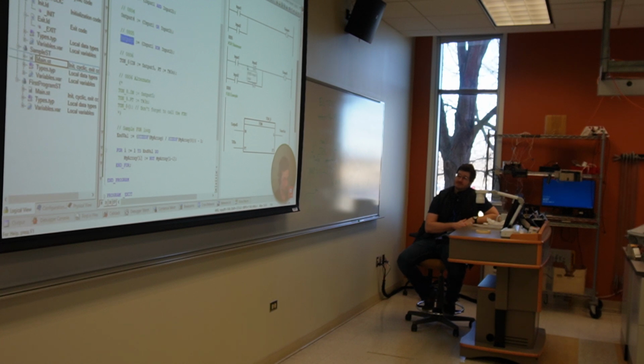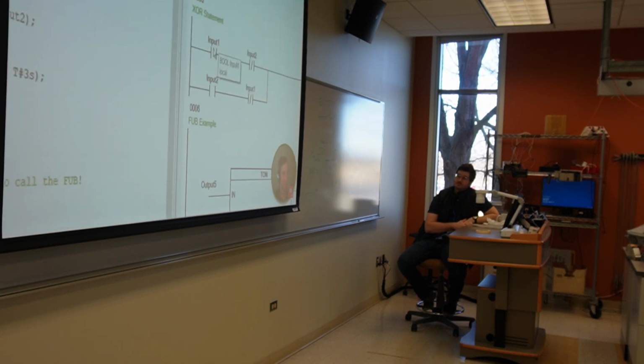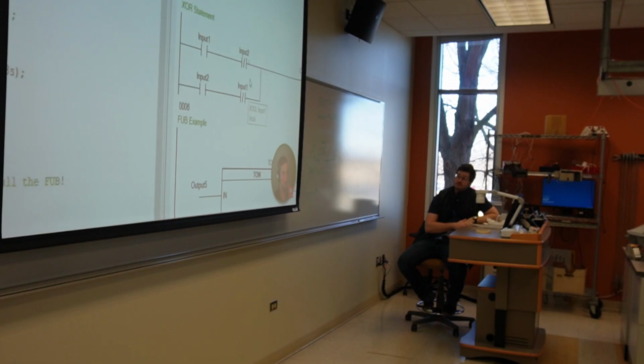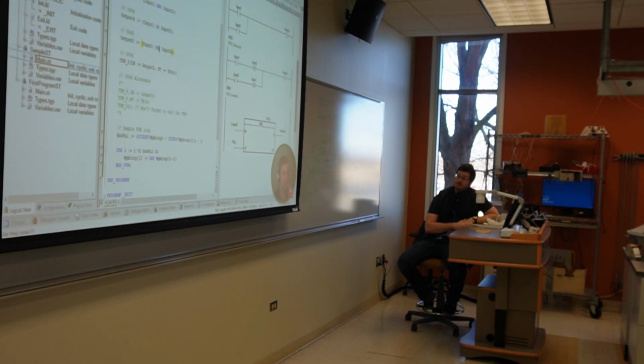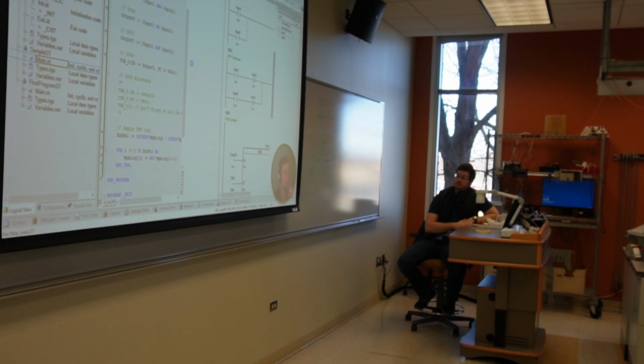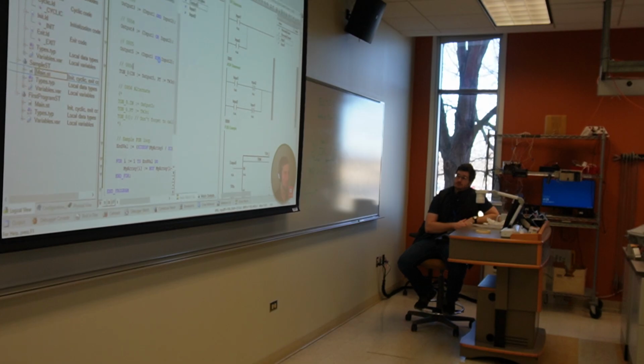We don't have to do this kind of funky, normally open, normally closed stuff. We can actually just type XOR. So that one's a little bit easier. So input 1 XOR input 2. And we can take a quick look at that just to prove that it works, since it's a little bit of a trickier one. As our watch window opens up here, I'll just drag output 5.